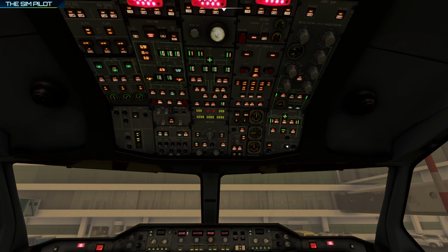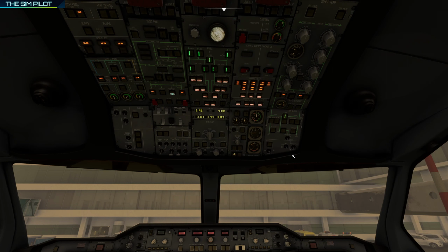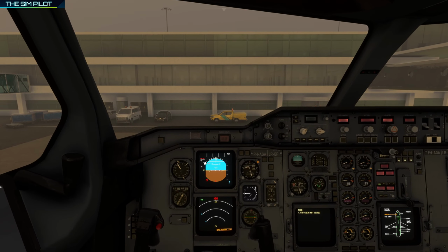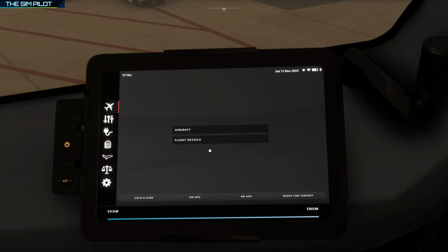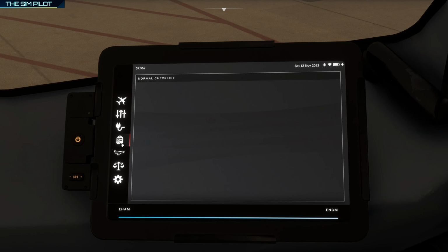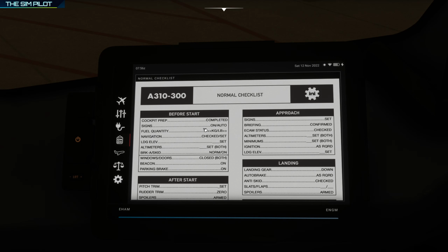That is now tested, and we can go back to bright, and we can turn on the standby compass light. It's a little bit dark, so I think it makes sense to turn it on. Alright, that's the overhead flow done. We have a checklist that we can follow as well, but we have a couple more things to do before we do the checklist. So we will finish these flows and verify it by going through the checklist.